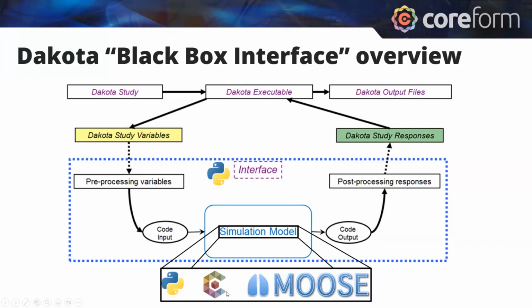It's going to run Cubit Python, and then using subprocesses, we're going to launch Moose. Of course, if you have Slurm on a machine, there are Slurm modules for Python, and you could use, I think it's called SlurmPy, and then run Moose from there. And then your results will be saved to a text file that DAKOTA will read back in and make its next guess or its next iteration. So really all you need to do is be somewhat proficient at Python, or at least able to modify template files that someone else has produced.